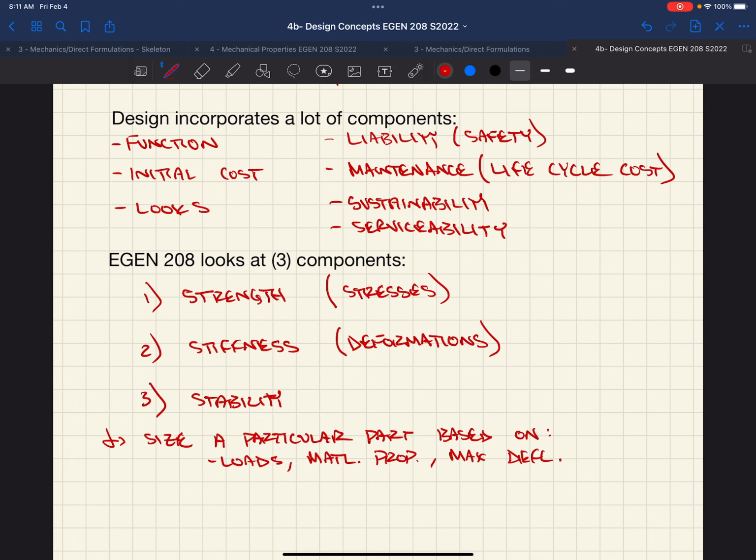If you go to a lot of the brick buildings on campus, a lot of the openings have what we'd call lintels, right? That support the brick. Those lintels have to be L over 600. So like really, really tight tolerances, right? So that's in order to keep the brick from cracking, okay? To give some perspective of this, an L over 100 is something that you can actually physically see. So L over 600 is very, very small.